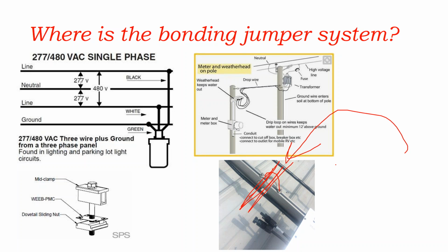Or you take a metal pier and you drive it into the ground, and then you put a metal racking on top of that. And you say, okay, well, I know when I use these specialized grounding washers, I am etching into the module frame and biting into the module frame. And so even if I have an anodized coating that can impact my connectivity, these grounding washers help me get through that so that everything's grounded together.